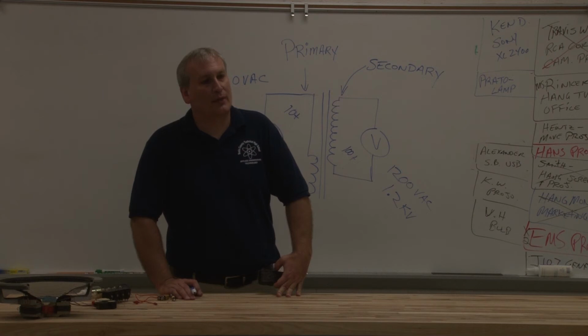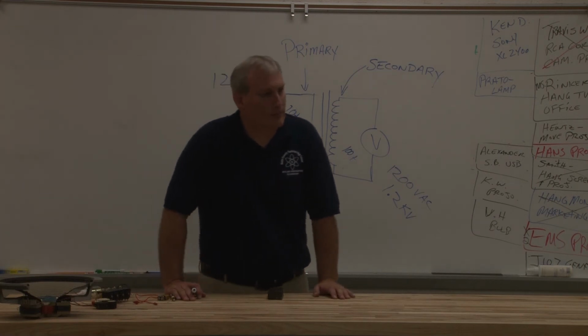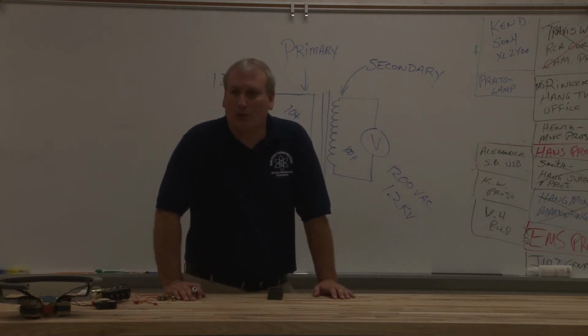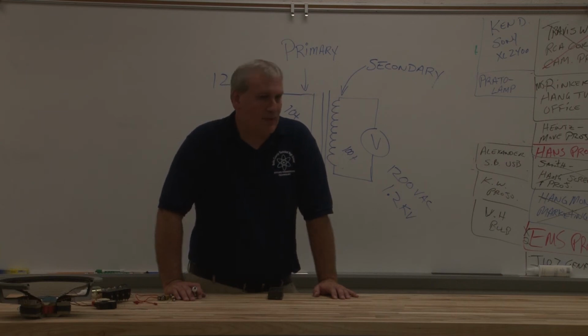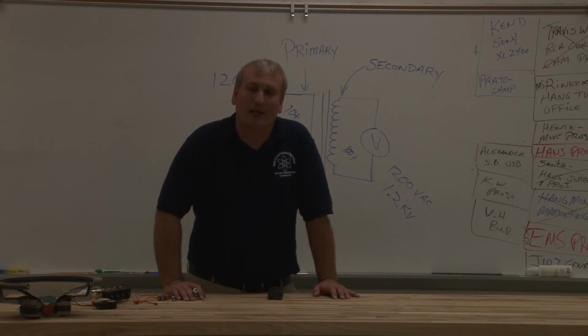Now another question for thought. If I can step voltage up, why can't I solve all the world's energy problems? Because it doesn't change power. Just keep stepping up voltage. Because it lowers the current if you step it up. Okay, very good. Dakota, what did you say? You can't change the power. Power's constant. Okay, you can't change the power. And John, what were you going to say? Pretty much the same thing?